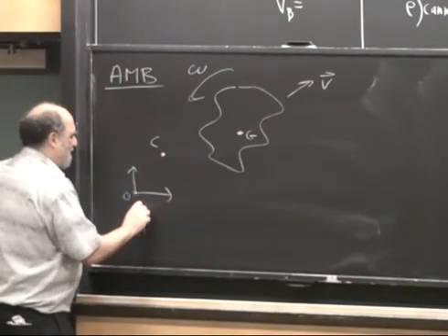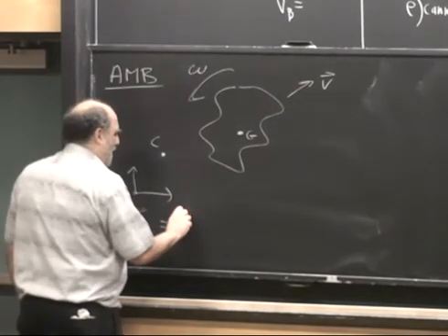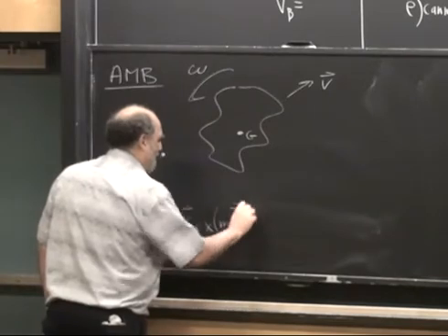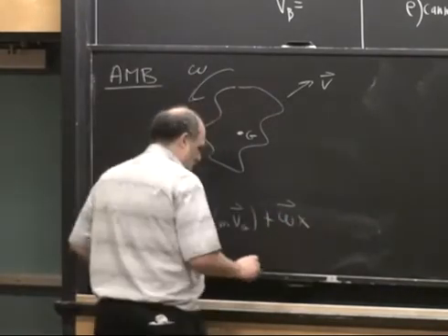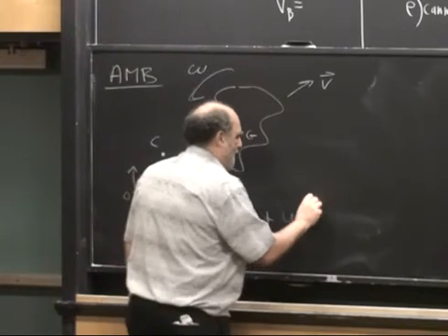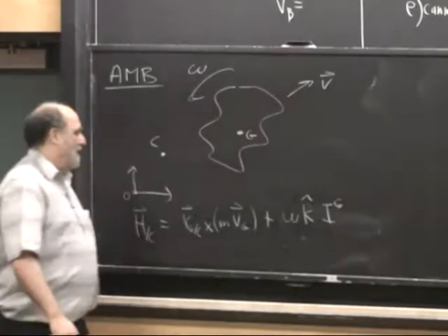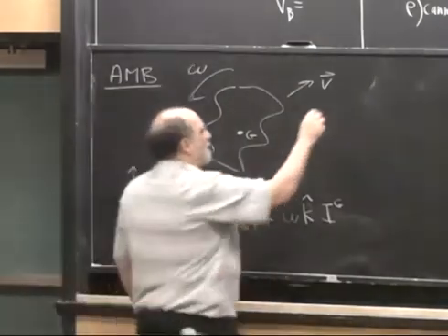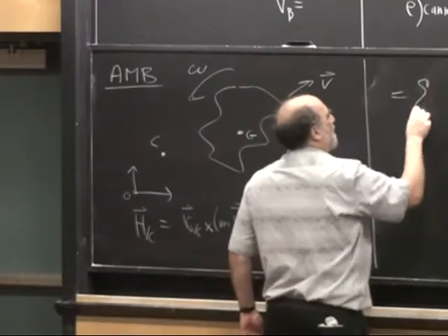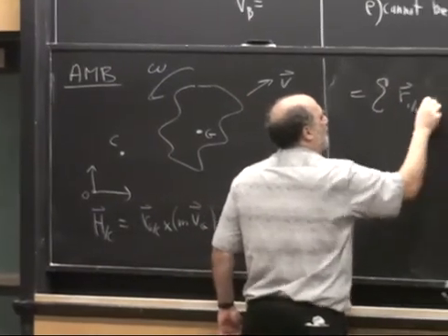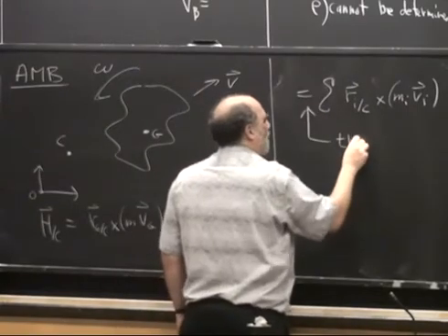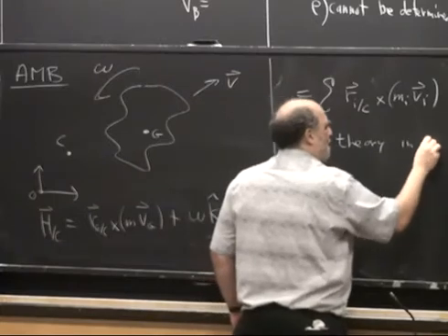The key quantity that we're interested in is the angular momentum with respect to C, which is the position of the center of mass relative to C, crossed with the mass times the velocity of the center of mass, plus omega k, and we multiply this by the moment of inertia I about the center of mass. Now this thing is a shorthand for the summation of the position of all the particles relative to C crossed with the masses of all the particles times the velocities of all the particles. And why these two things are equivalent is a little bit of algebra which is in the text.